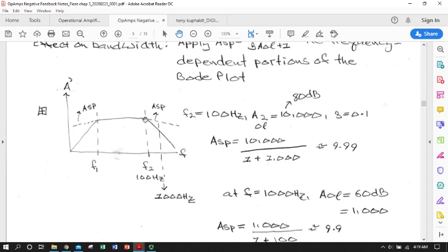So up till now, we've just simply measured it. We've maybe calculated our F1 and F2, especially our F2, based on some knowledge of the capacitance and real resistance of the circuit, using what we know about impedance and our AC active and resistive component addition. But we haven't looked at the effective feedback. We've only looked at those calculations from the standpoint of an op amp operating all by itself. So now we're going to start with a little bit of a comparison to get an idea of the power of negative feedback when we want to operate in this region.